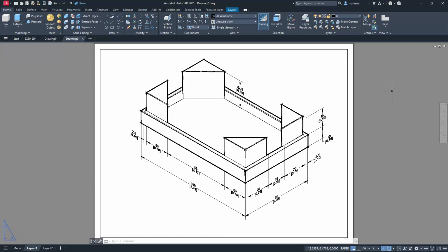Remember that this is a huge advantage that you have over any of your other 3D programs, is that, as far as I'm concerned, or as far as I know, AutoCAD is the one that typically can do this. Now you see that it does take a little bit of work, but this drawing accurately depicts what you want to happen if you're creating a drawing with 3-dimensional views. This shows everything that you need. And you probably would be able to give this to some fabricator, and he should be able to produce this. So sometimes an isometric is a nice simple drawing, but usually they're used for pictorials. And in the rare occasion that you do want to dimension them, this is how you would do it.